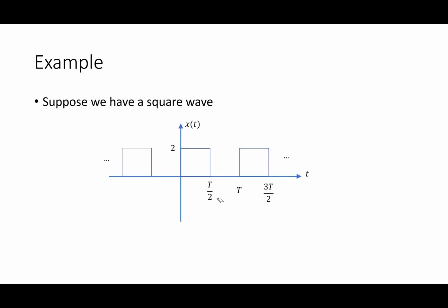Okay. So back to a waveform. Let's apply this now. If I've got a square wave here, I want to apply this alpha n equation: alpha n equals 1 over T, integral from t to t plus capital T of x of t e to the negative j n omega naught t dt.